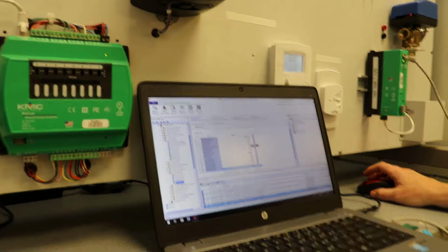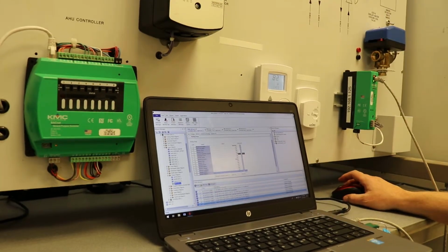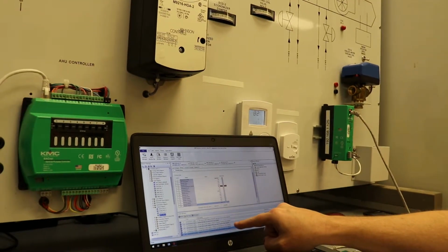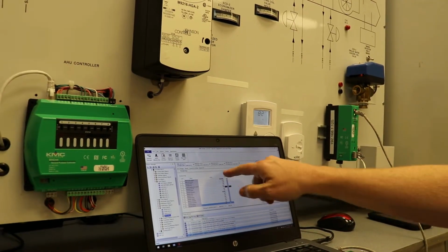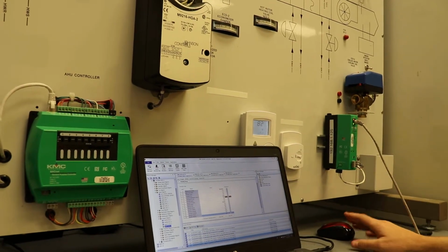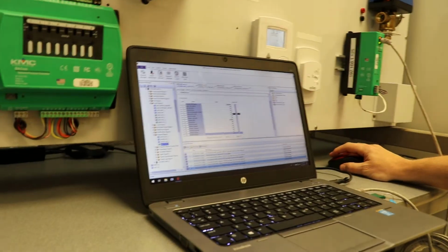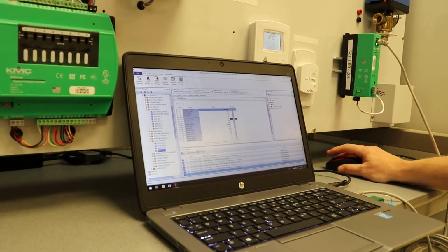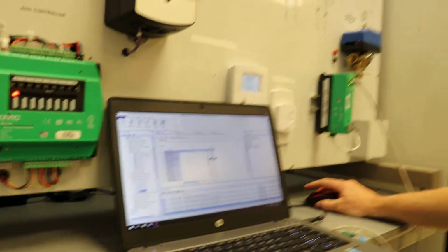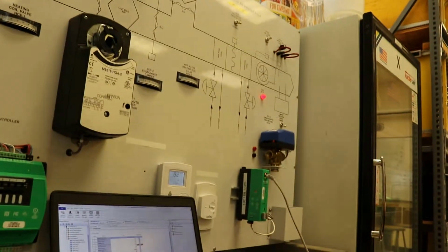So you can have up to 16 things telling this one output what to do in descending order of prioritization. So of course anything at 1 trumps anything else below it. It's emergency. We're turning this thing off. There's a problem, and our software writes it priority level 9. So if you just click on the box here, hit relinquish selected. So now the software took over automatically, and turn it back on.